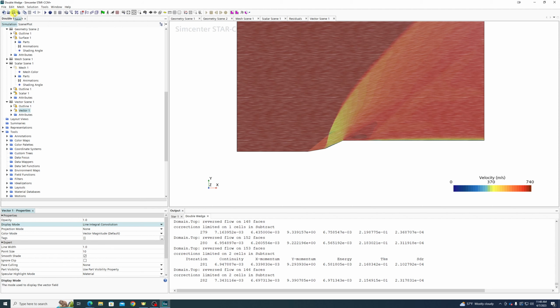We will have an assignment that is similar to this in the near future. It will be something that you can validate with basic shock angle and Mach number predictions, with basic supersonic flow math, which is actually very simple compared to subsonic flow math. You should be able to validate your supersonic simulation and make sure it's doing what you expect, at least pretty closely.